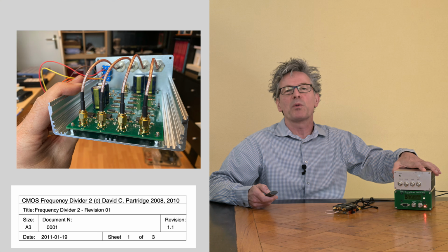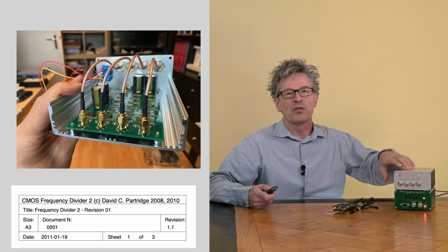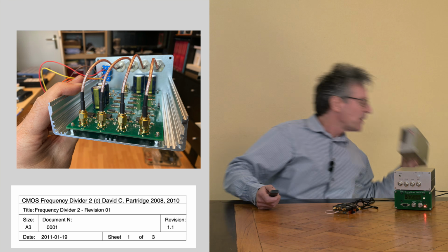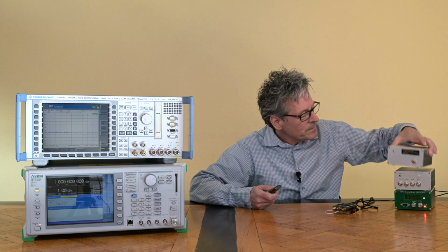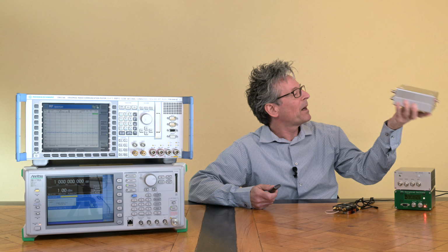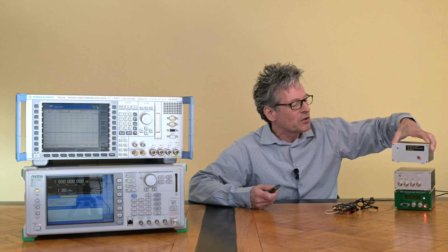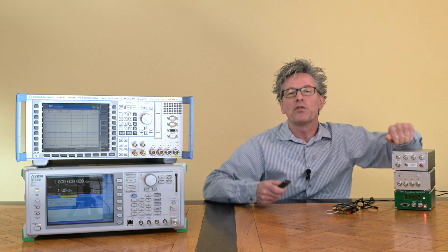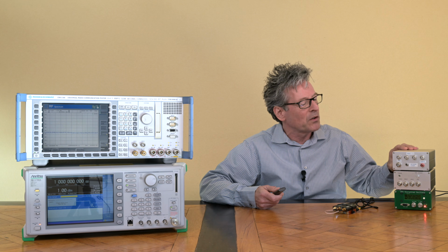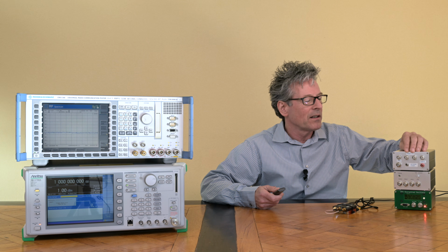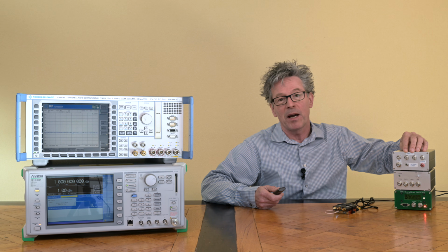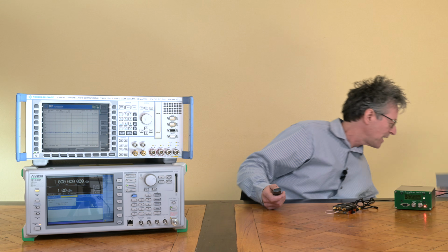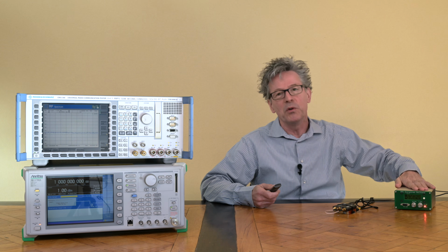It's also a nice project to exercise a bit of SMD soldering, which is one of the reasons that I did it. I also built a clock distributor for my lab. It has six outputs, and this way I can connect a variety of my devices to the same reference clocks, and all the outputs are electrically isolated by transformers to prevent any ground loops. So these are fun things that I built on top of my unit here.